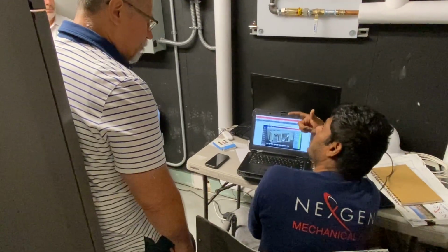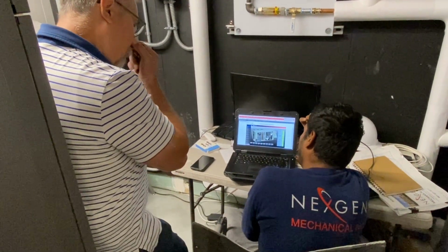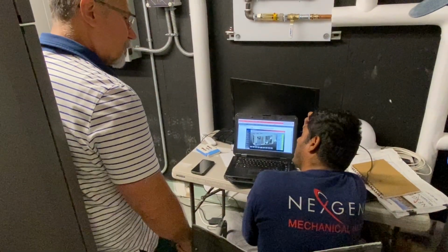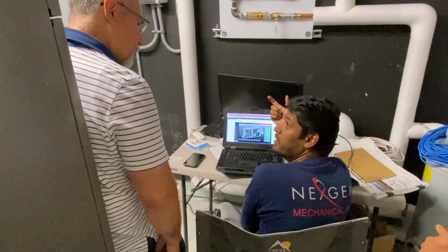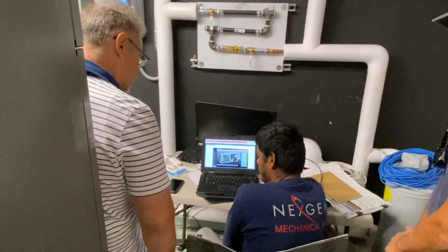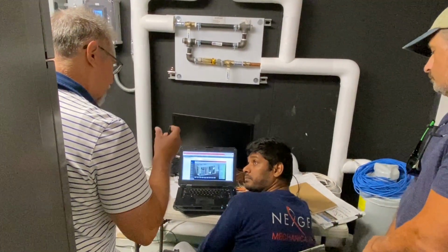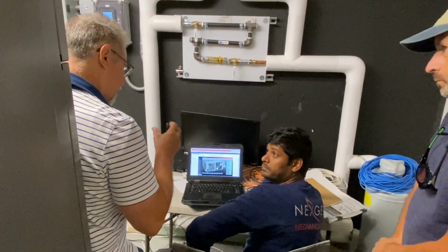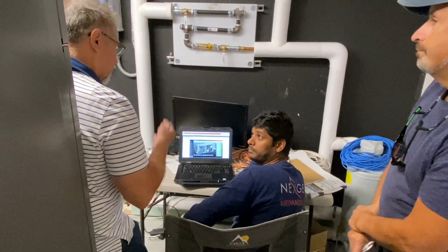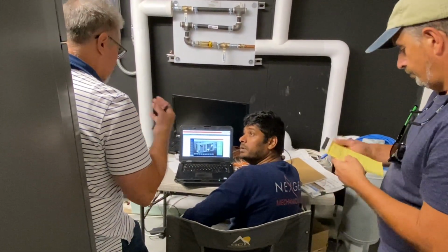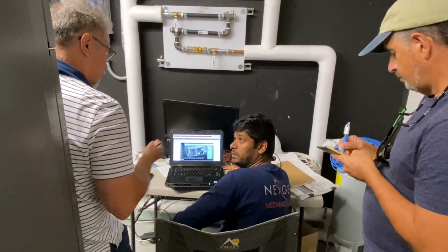So that's a CO2 control, and we talked about the warm up, and we talked about the cool down, and of course the discharge air set point is based on the OA reset. So outside air reset. Yes. Okay. Also, does it take into consideration if my rooms are overheating? So let's say five rooms, 5 VAVs, 3 of them are overheating. Does it change my cooling set point automatically lower to try to cool those rooms?